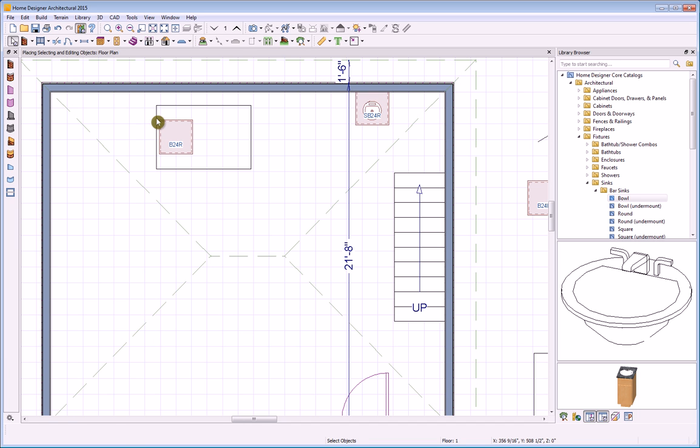If I click right here, for example, I select the slab. I want to select the cabinet, so I'll press the Tab key on the keyboard. It will cycle through all other nearby objects, and now the cabinet is selected. You can also click this Edit button, the one that says Next on it. Each click cycles the selection to the next nearby object.